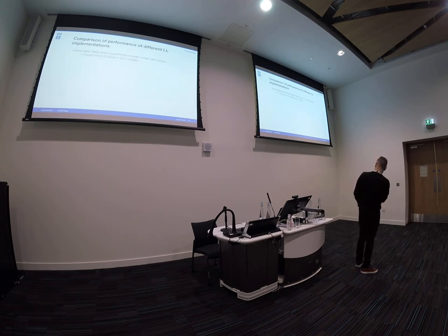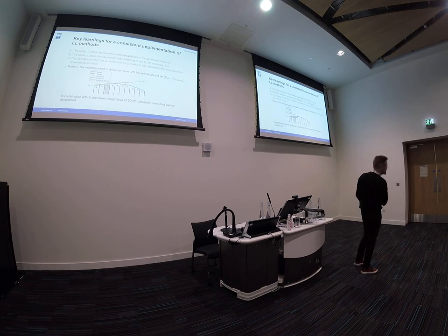the right velocity to look at when you do the lifting line stuff is the total 3D induced velocity from the system minus the local 2D bound one, because that's already included in the thin airfoil model itself. So this is the velocity that the inner 2D section should be using for this to be consistent. So then you evaluate that difference velocity at the three-quarter point there at the cross.